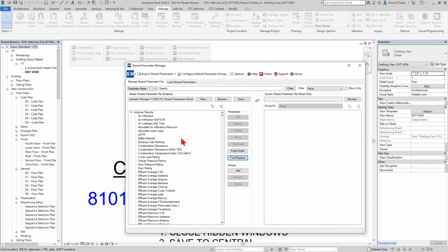By the way, to clarify, why don't I recommend putting initials as prefixes? This is why. The family processor up here, this extra tool that you can use to go through all of your content and fix all of it to make it your shared parameter. One of the things that this will also do is when you get other outside content in the future and you go, oh, hey, look, here's a parameter that's called panel width, right? Everybody in industry in English typically calls it panel width, or maybe it's door width, whatever, but it's common language. Nobody's going to call it CTC underscore panel width. So if I prefix all of my corporate parameters with CTC underscore, the problem is that every time I go into Family Processor, I will have to manually browse to my parameters, and there will be no easy way for me to get to P for panel width because the first 4 characters are CTC underscore.